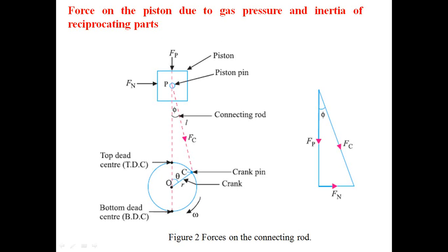As you know, when theta increases, then the component Fn will also increase. This is the line diagram of the forces Fp, Fn and Fc. The root cause of the forces Fn and Fc is Fp, applied due to the gas pressure.